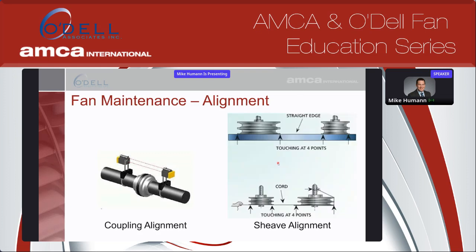And if you don't have a laser alignment tool, you can still kind of use old techniques. A lot of people use a string, and this is kind of an example of the string on the bottom here. And you may need an extra set of hands for some of these, especially with a straight edge if you have long belt centers. But there are other ways to kind of look at sheave alignment without having a laser. So these are okay practices. Obviously, the best would be a laser typically, but there are other ways of making sure sheave alignment looks good, so you get the best longevity out of your belts, and you're also not putting the wrong kind of forces on your motor shaft or your fan shaft.